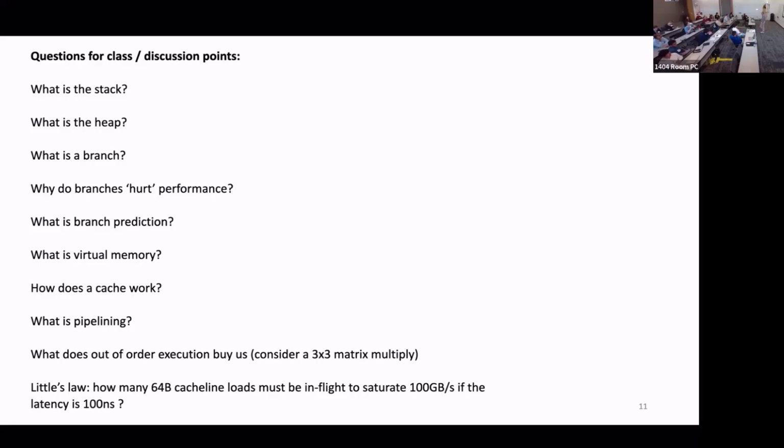So this actually dictates one of two things. Either you support a prefetch and a very, very deep either software or hardware prefetch where you can generate many requests independent of the load sequence of the chip, right? So you don't couple the register filling to the fetching from memory. You have a decoupled architecture, we call them. Or you have a huge number of registers, and even then it's kind of hard with a single program with dependencies to generate that number of pending loads.